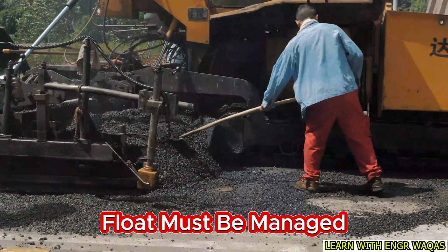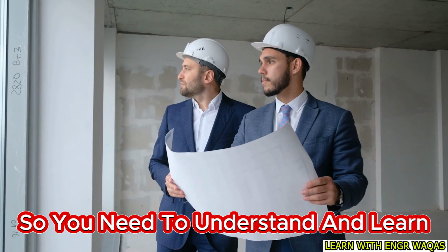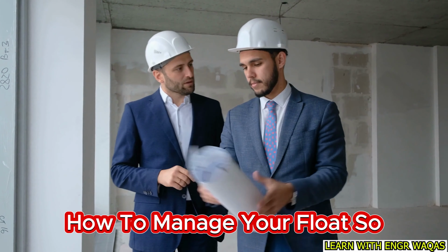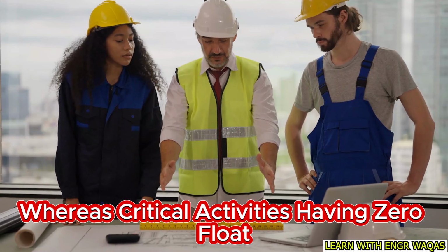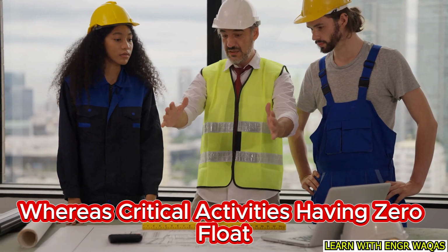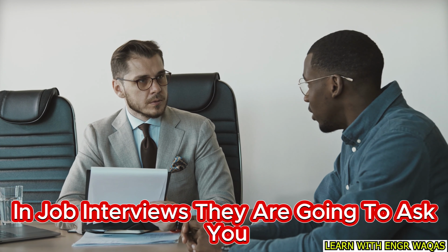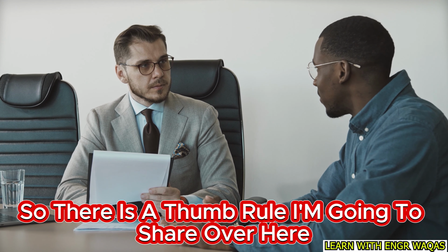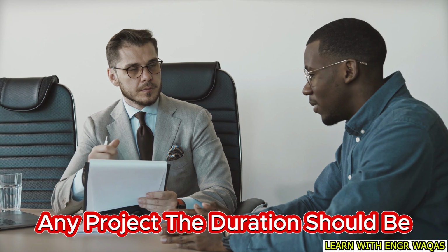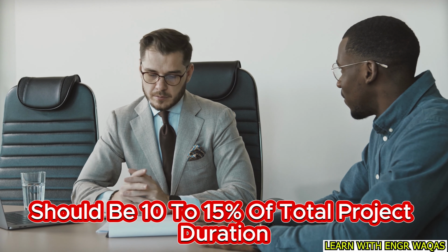Float must be managed. Float is the amount of time an activity can be delayed without delaying the project duration. So you need to understand and learn how to manage your float. Float is always the property of non-critical activities, whereas critical activities have zero float. And there is one more thing I'm going to convey over here. In job interviews, they are going to ask you what the float limit is in any project. So there is a thumb rule I'm going to share: in any project, the float should be 10 to 15% of the total project duration.